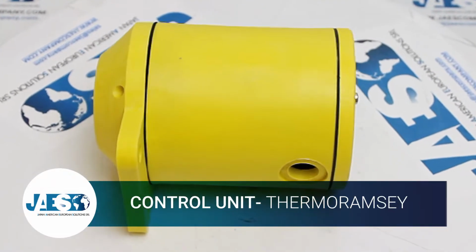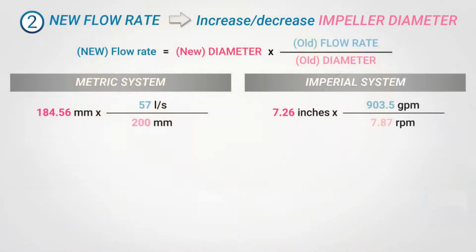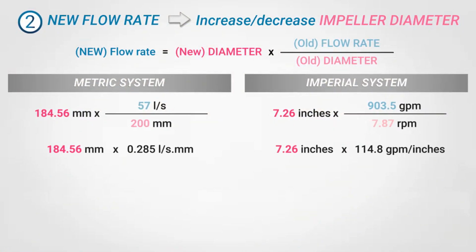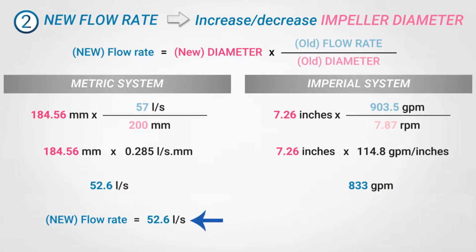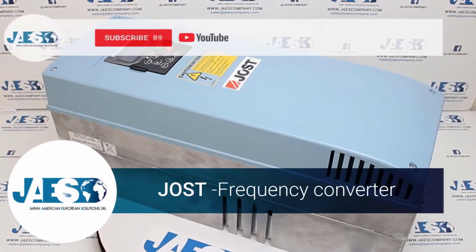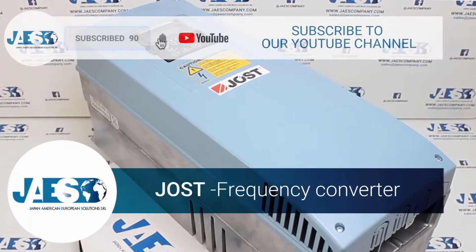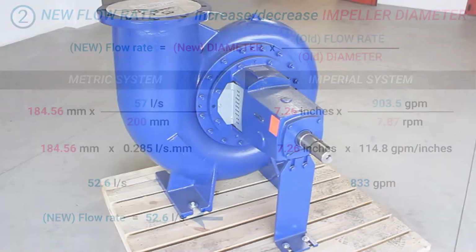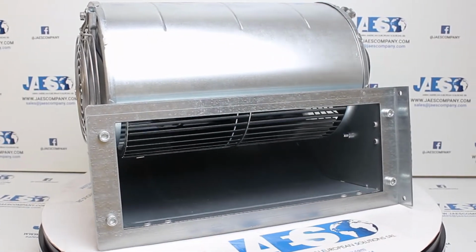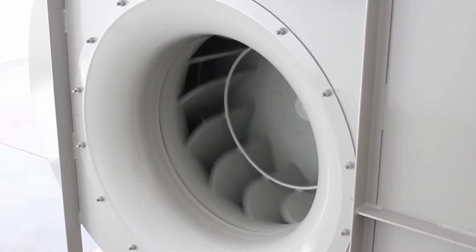A more complex type of inverter is necessary when it is integrated into a frequency converter or into a control unit to manage and control the speed, torque, and direction of AC motors. As we saw in our previous video on the sizing of centrifugal pumps, a practical way to change the rotation speed of the pump impeller is to use a frequency converter to maintain unaltered the other design parameters. It is common to find inverters used for the control of pumps, fans, compressors, and in basically any rotating equipment.